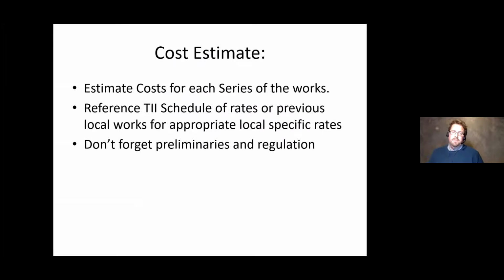So your cost estimate, how are you going to pay for this? Who's going to pay for this? So estimate the cost for each series of the works. So your cost for your planing, your cost for your material removal, your cost for your fencing, your cost for your bituminous binder, for your surfacing, for your base, and work through the whole lot of all the series. They're laid out very carefully in the TII's schedule of rates, and reference back to the schedule of rates, what cost the TII are getting.